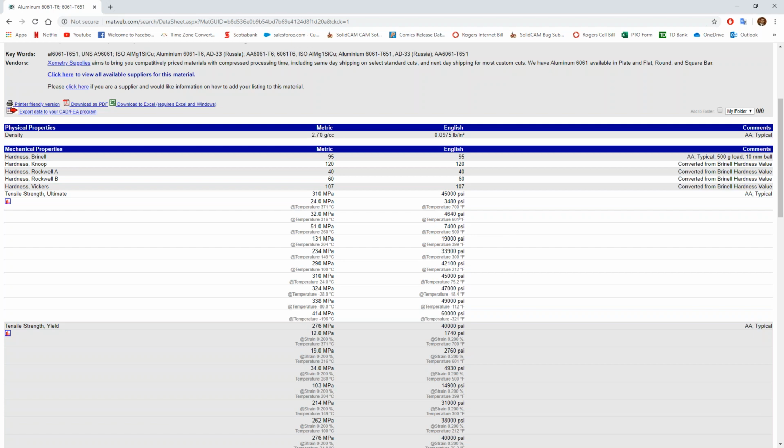So maybe when you're using a certain vendor, that machinability factor needs to be at 20%. And when you're using a different manufacturer for the same material and everything's the same, that manufacturer needs to be at, like what Mark was saying, minus 14%.